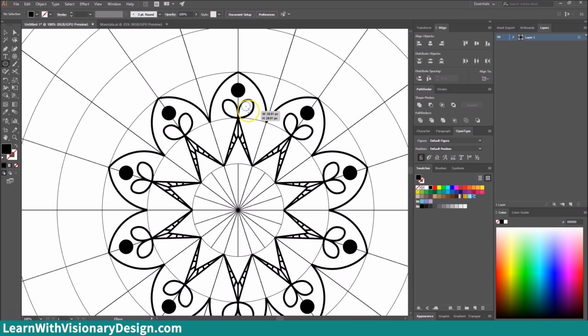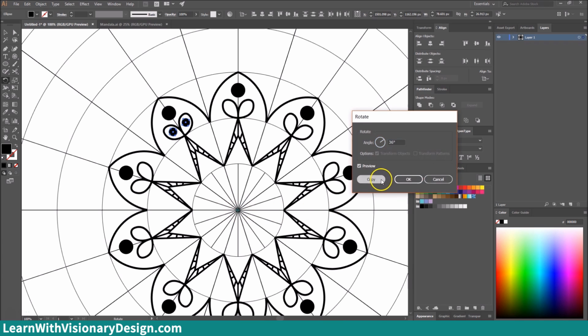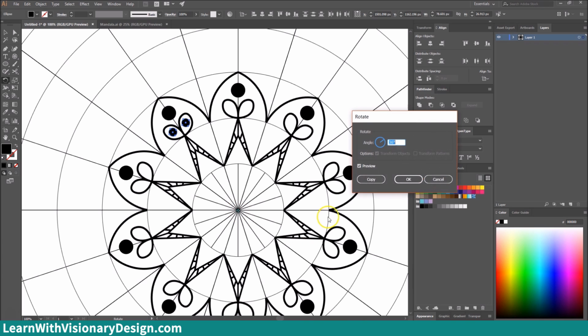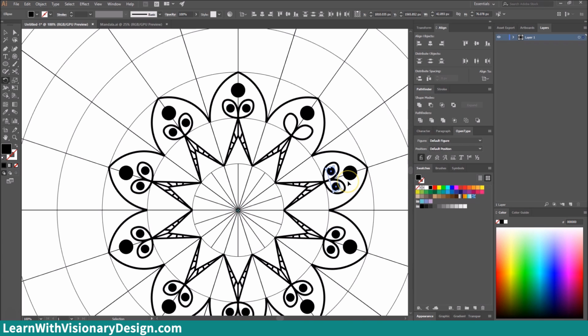We'll make a similar process by creating circles inside those shapes we created earlier. Press your Alt key and hold on the circle, then Shift to duplicate and drag it horizontally. We'll also duplicate it in the same way. Oops, we'll see here that the angle wasn't correct, so this means that we didn't click right on the middle. Now it's better.